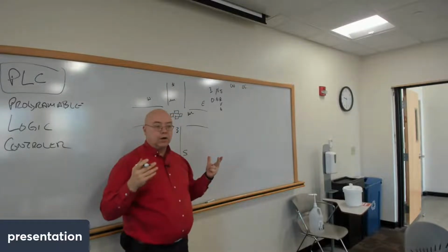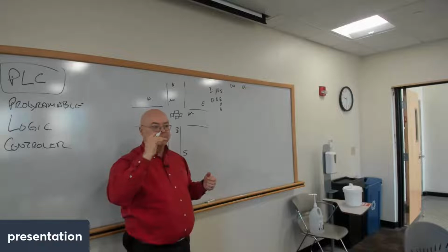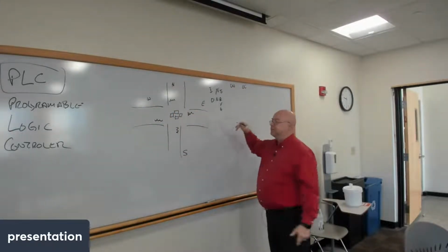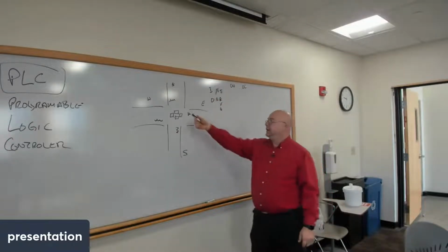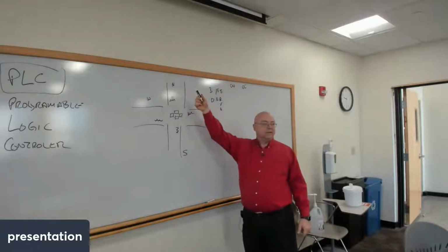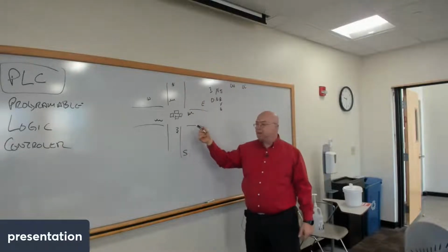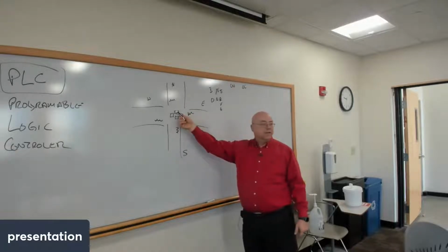And then you've got a program that it steps through, and you lay it out as a ladder. So the first thing you do is check which sensors are active, right? If this sensor is active, then you know that there's a car there. But you've got to also say, if this sensor is active and this light is green, then you don't do anything, right?